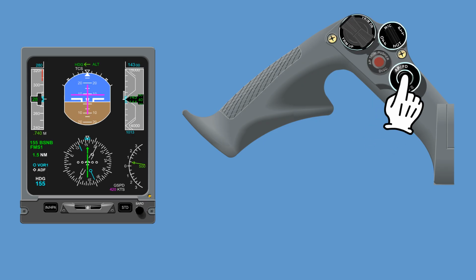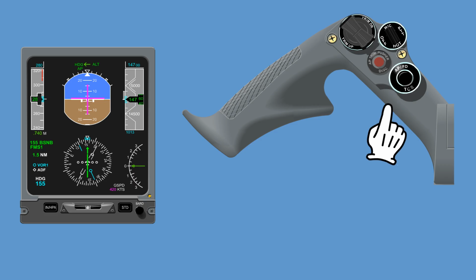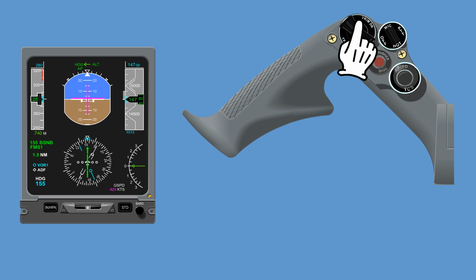Pushing the touch control steering button allows manual maneuvering of the airplane to any pitch attitude without disengaging the Autopilot. After the button is released, the primary servos will re-engage and the computer will synchronize to the new pitch attitude. Manual trimming of the aircraft is performed through the pitch trim switches. The operation of a pitch trim switch will disengage only the Autopilot while the yaw damper remains engaged.